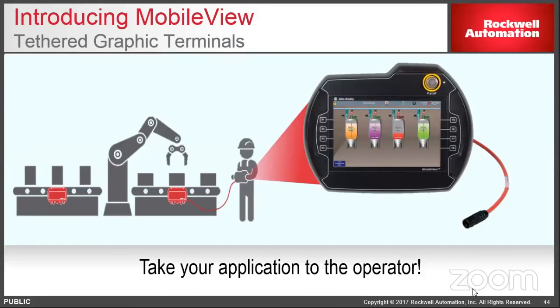So I'm not going to spend a ton of time on this. It's kind of a departure from our normal types of panel views, which get installed in an enclosure and a panel. We're switching now back to a FactoryTalk View product. This is part of our on-machine offering. What Rockwell considers on-machine is something that does not need to go in an enclosure at all. It's completely sealed, IP65 and above. My demo unit here is plugged into an IP65 sealed box with an IP65 power supply. It's for customers that are getting rid of the enclosure, getting rid of panels altogether.